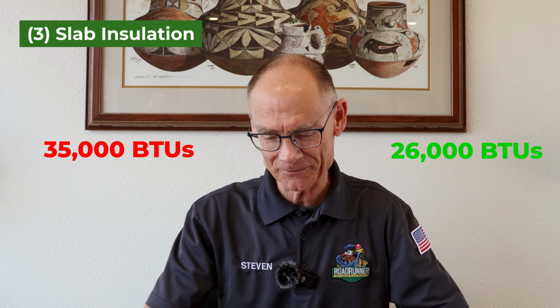It is a 24% improvement on the heating loads. It actually lowers the heating BTU requirement from around 35,000 BTUs to around 26,000 BTUs. 24% improvement on heating loads and a 5% improvement on cooling loads. So that is the biggest improvement so far out of these three.